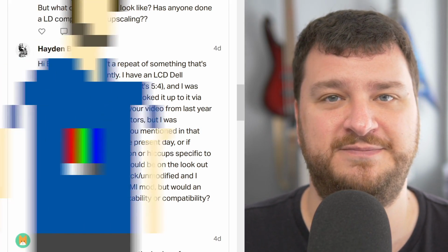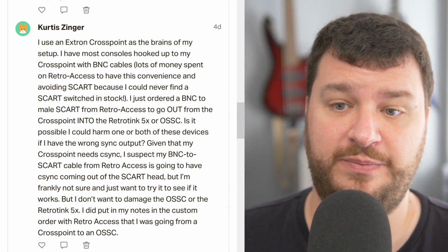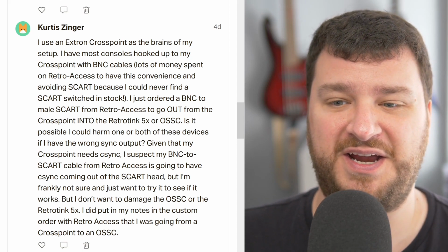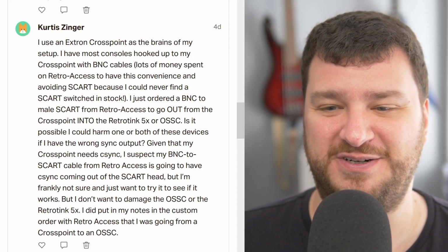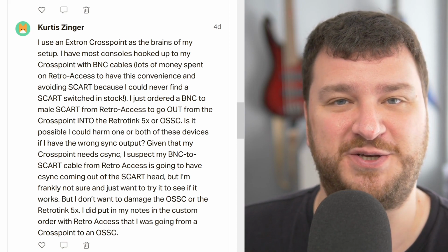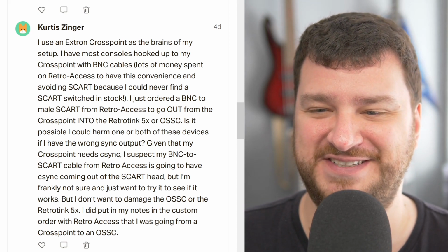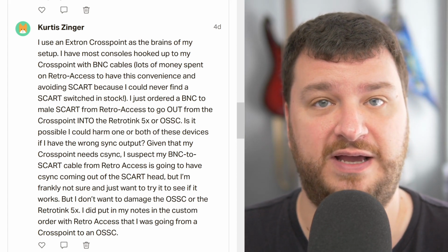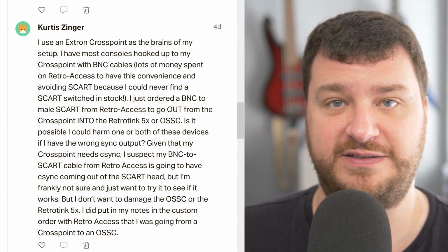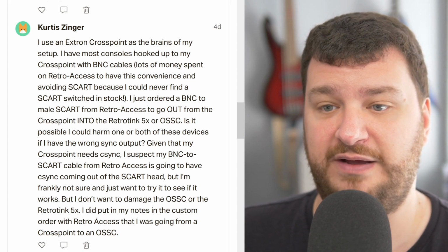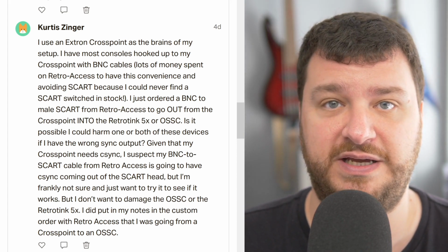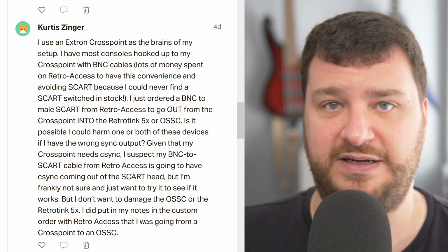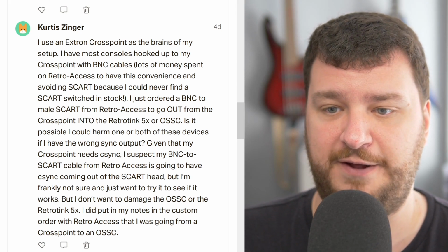So no worries there. Curtis Singer has a question about using an Extron Crosspoint with their setup, and just to make acronyms and terms easier to understand, I'm going to skip reading the question and just go to the answer. I mean that respectfully, obviously. But in order to use Extron Crosspoints, at least the ones that I've used, you need to feed it C-Sync directly. You can't feed it composite video as sync or Luma as sync. And that's just a compatibility issue. That's not like a quality issue or anything like that.